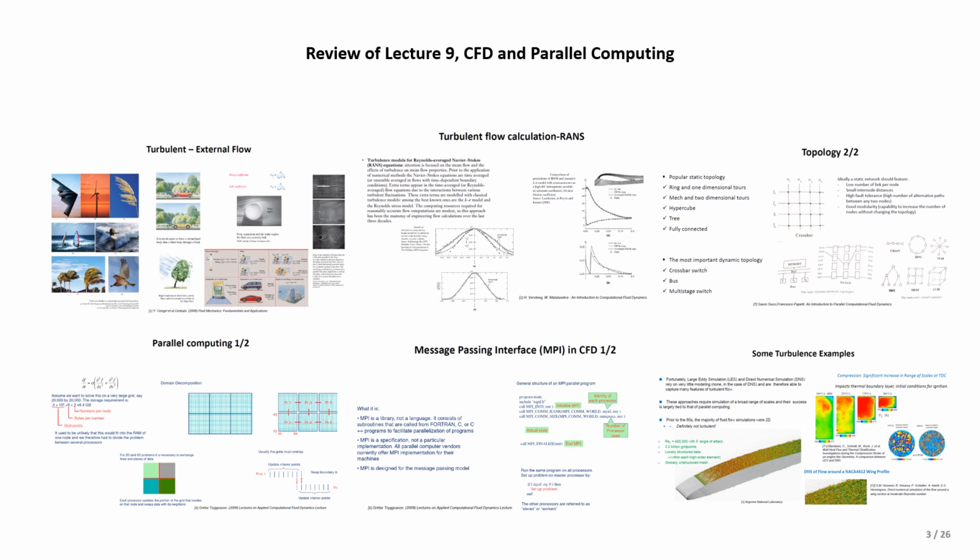We looked at the available computational fluid dynamics methods for turbulent flow: Reynolds-averaged Navier-Stokes (RANS), large eddy simulation (LES), and direct numerical simulation (DNS). We had examples from these three main categories. RANS is usually used in industry, and it provides an average solution.